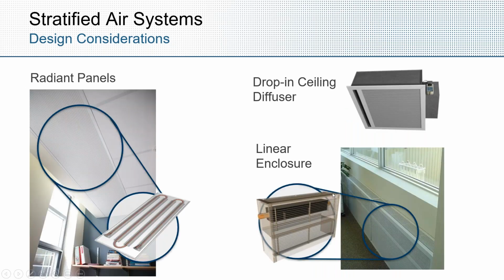So again, just want to note a couple of differences there. Now, everything we've talked about up to this point is cooling related. For heating, of course, you don't want to heat into the space with a high delta T at low velocity. We all know that, especially from Ryan's discussion, because that's going to short circuit. That's going to cause issues with that warm air rising naturally immediately up out of the occupied zone.